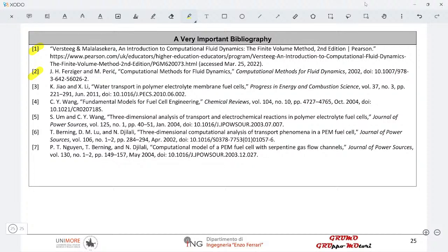Yes, you are reducing the number of cells, but solving those equations on a lower number of cells, and at the limit one centroid, might create a lot of numerical instabilities in terms of fluxes at the interfaces. So if you do not have stability issues, you might introduce some simplifications in the local resolution of the flow at your gas channel. In this way, you might contain the total number of cells, and so your total computational effort for a full stack.